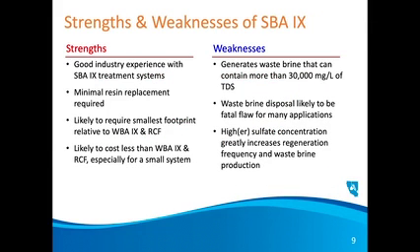And so the strengths about it is that it's a common industry experience. You need very little resin replacement, and I say minimal because you lose resin through backwashing and regeneration, so you have to replenish every year, replenish a small amount of that resin, depending on the loss rate. It is likely to require the smallest footprint compared to the other two processes, and it's likely to cost less than the other two processes as well, especially for a small system.